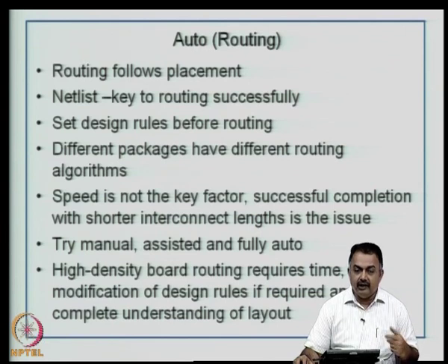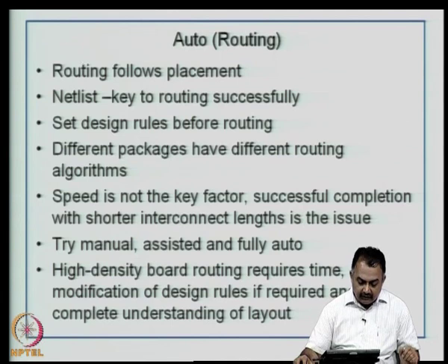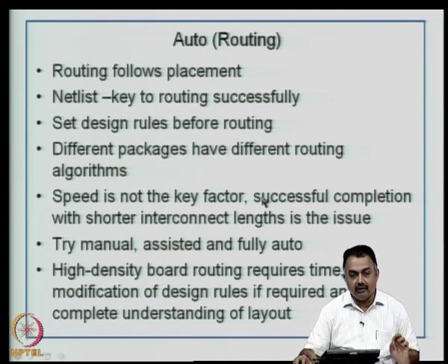Now, in a very dense board, you can give at least 5 to 6 passes and compare which one is efficient in terms of the design rules that you have set. This is time consuming if it is a high density board, which is very normal. Speed is not the key factor. Successful completion with shorter interconnect lengths is the issue.